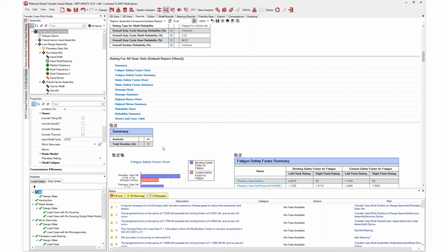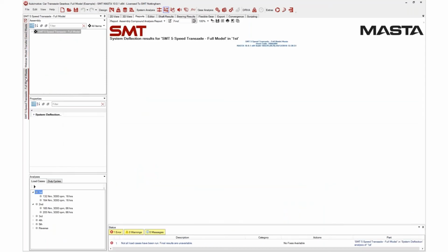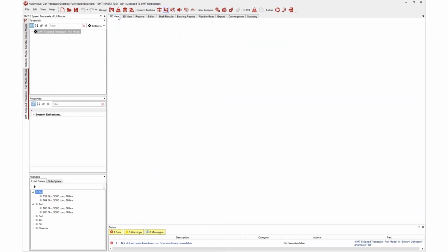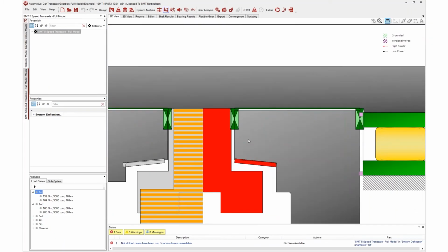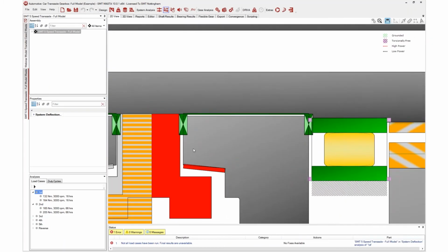For the left and right axial clearance bearings, yes, something that I missed there. If I go back to this other model here, the axial clearance bearings will only work in a single direction. So if we go back to exactly where we were before, this axial clearance bearing here will have a clearance, and that will only happen going, as you can see on your screen, from left to right.